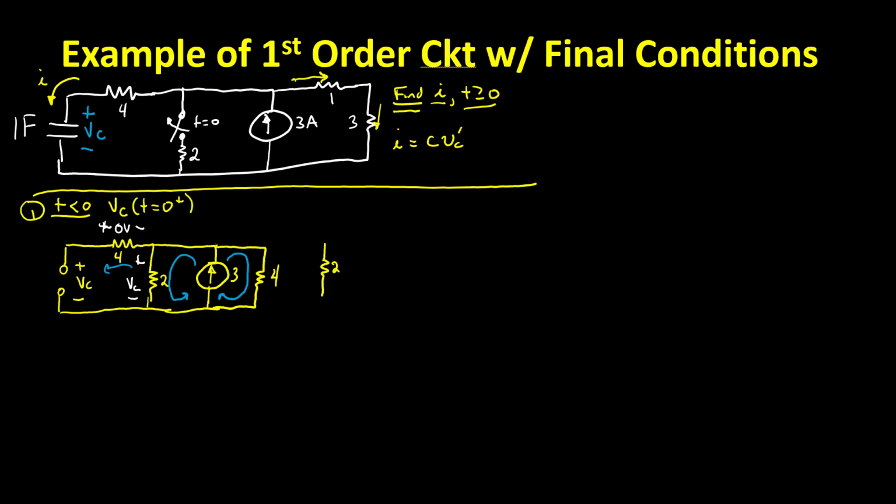But I'm really not. Watch what I do. In 2 steps, if I firstly just move my resistors to one side of that current source, I get this, 4 and 3. And I think it's pretty clear that that does not change what VC is at all. I haven't changed my nodes at all. I have 3 current carrying nodes over here, and I have the same 3 current carrying nodes over here. So if my nodes haven't changed, my voltages haven't changed at all either. And you can see that combining these two does not change my voltage, because I could redefine where I pick off that voltage between here.